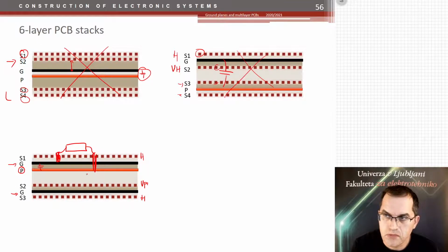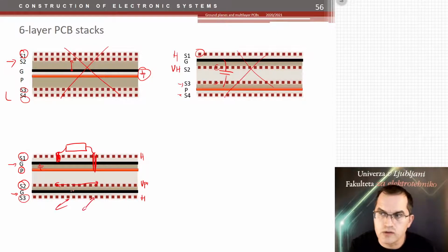So that arrangement is quite good, but then what you have is, of course, only 1, 2, 3 signal layers, not 4. Maybe you should also take care that these go left and right, and these are back and forth, so that they do not cross couple too much. Maybe you should interleave the signals.